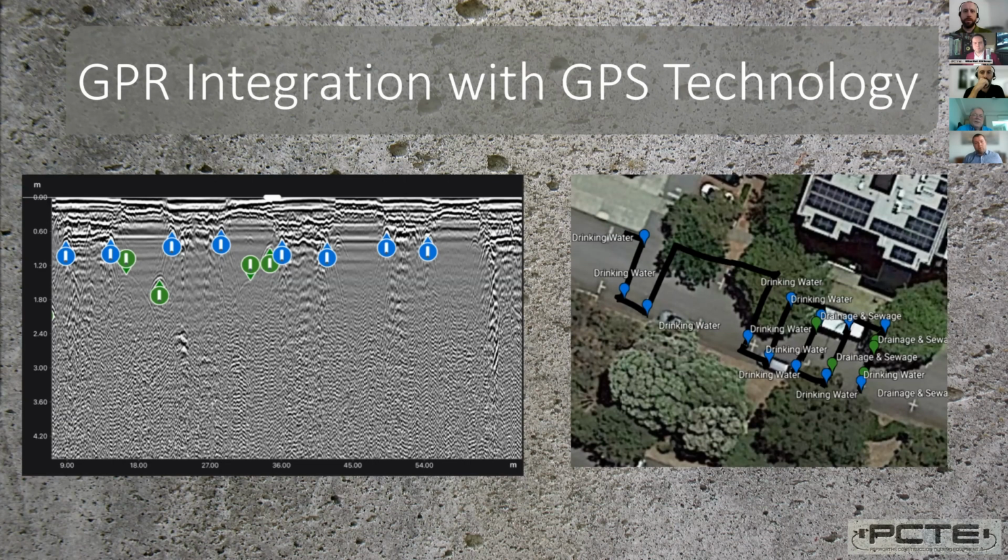So currently with the GS8000, we have a GPS that's included with it and integrated into the GPR. As we're collecting data and marking targets, the depth of each target and the GPS coordinates are recorded. Then we can send that information to customers in several different formats. They can open it in survey management software or in Google Earth, which is what we've done here on the image